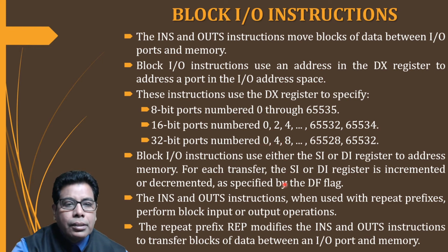So since these block instructions are used to transfer a block of data or string of data, we'll have to make use of the SI or DI register to address the memory where the data may be stored or from where the data will be taken.